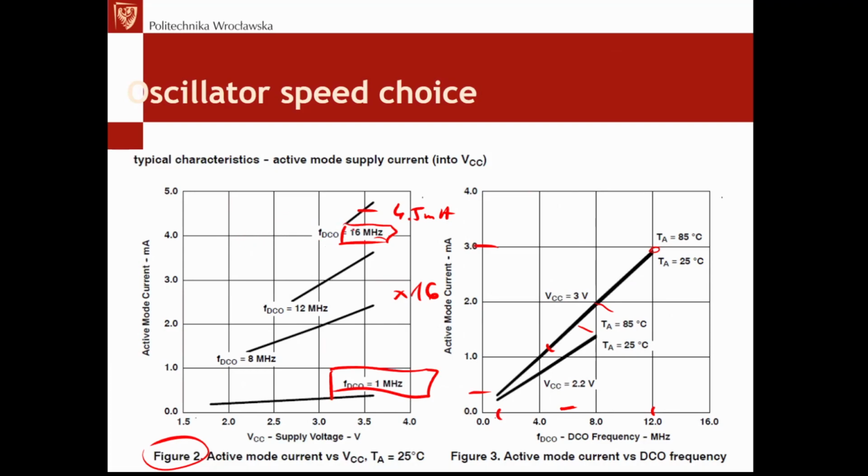The difference, and that's quite standard in case of microcontrollers, let me wipe it a bit, is that if you want the highest clock frequency, then you must supply the microcontroller, in this case, from 3.3 to 3.9, or now it's not even 9, it's here about 3.7. This is the usable voltage range.